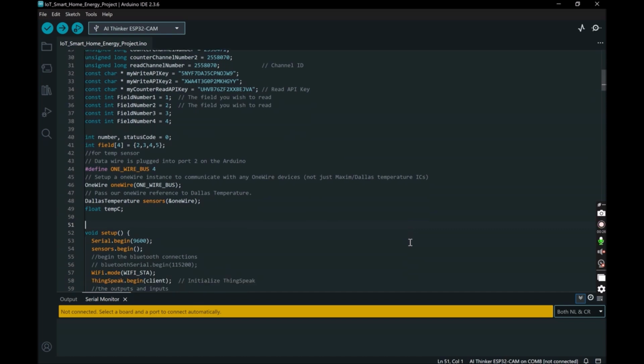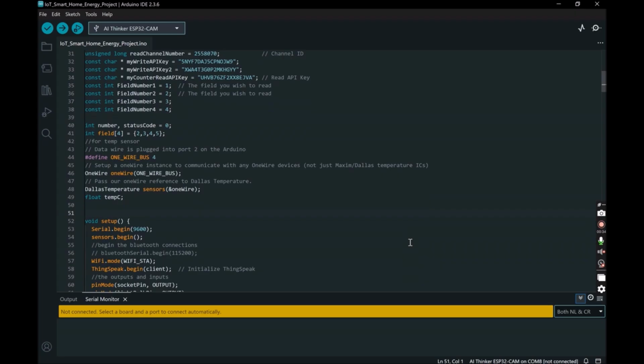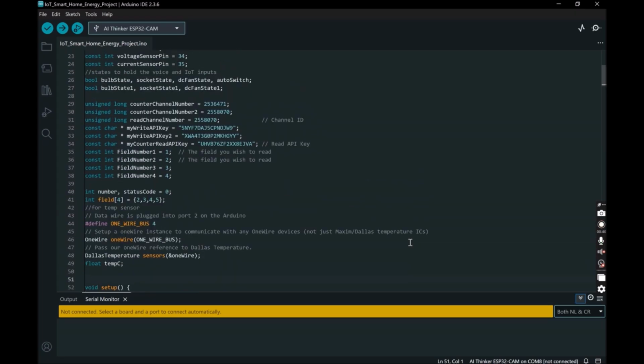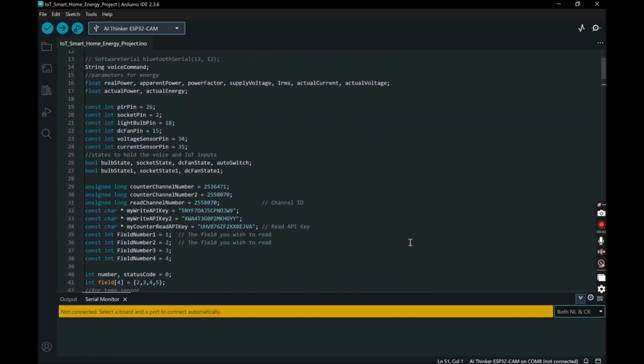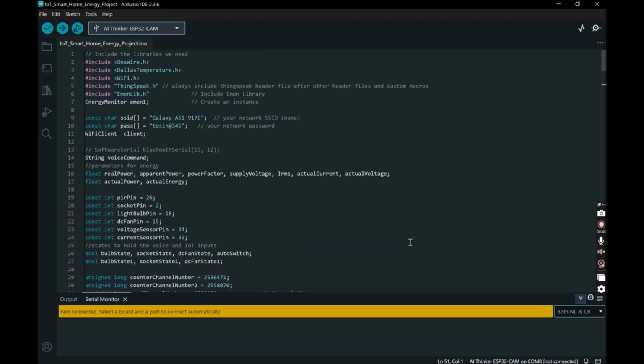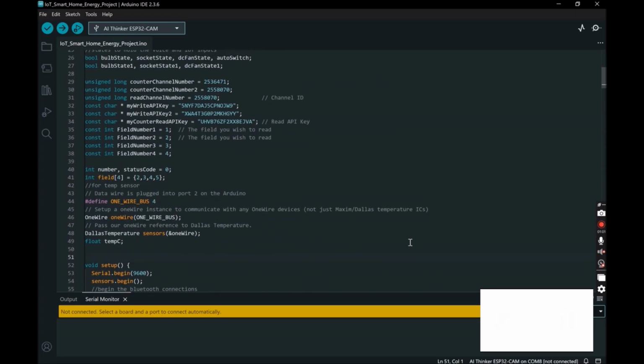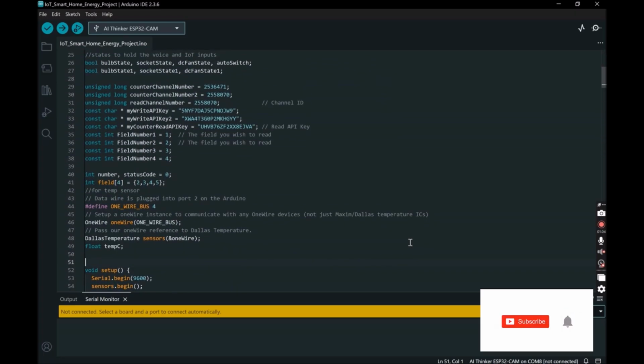So this is the Arduino code that was used to program the ESP32 for the project design. We declare a couple of variables to hold our ThingSpeak channel, since we use the ThingSpeak channel to send the sensor data and then read it up from our app. Then we also send the input button IOs to another ThingSpeak channel. So that is the channel declarations we did here.